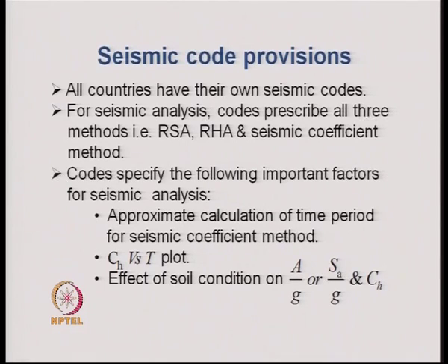These cases typically include the cases where we wish to study the behavior of the structure in the inelastic range. As you will see later, for most of the designs accomplished for structures for earthquake, we deliberately allow the structures to get into the inelastic range for the design earthquake level.